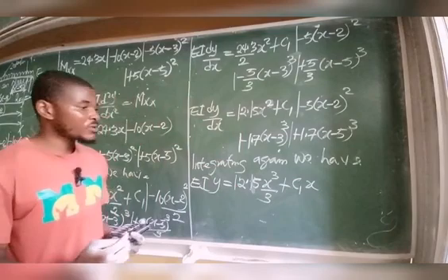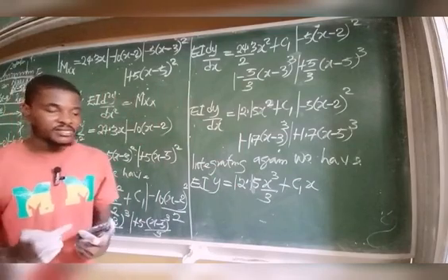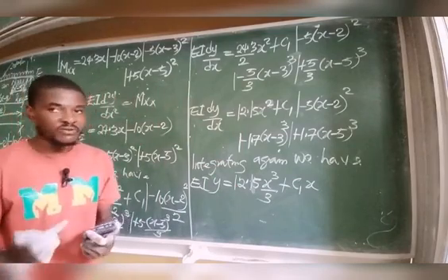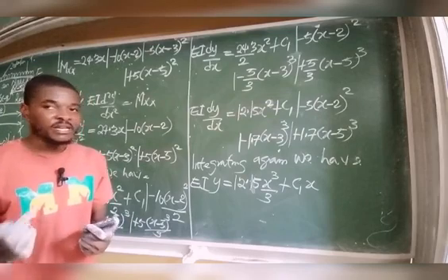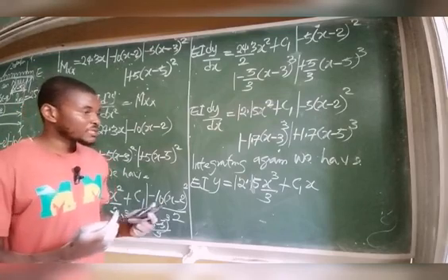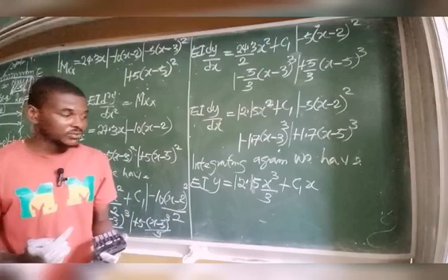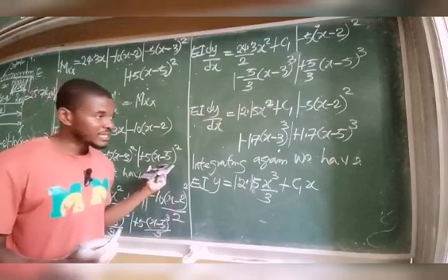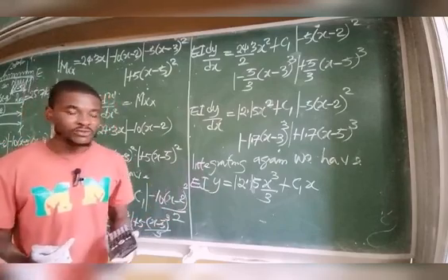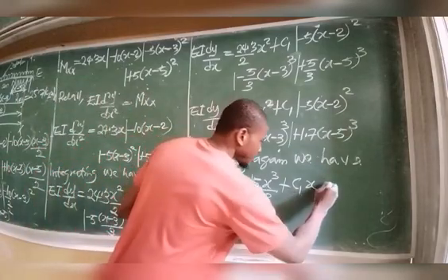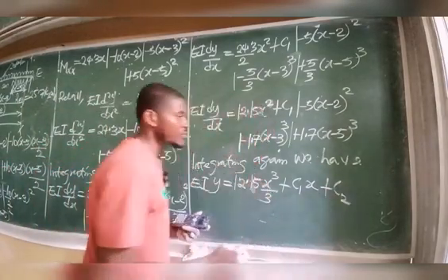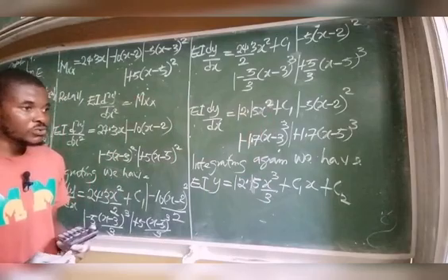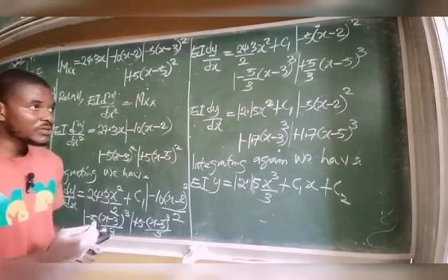Now, of course, according to Macaulay, you don't add constants inside of the Macaulay's bracket. It has to be added outside the Macaulay's bracket. So I also need to introduce the second constant of integration, because I've taken another integration. That constant is simply called C2, plus C2, the second constant of integration. It should also be outside the Macaulay's bracket.